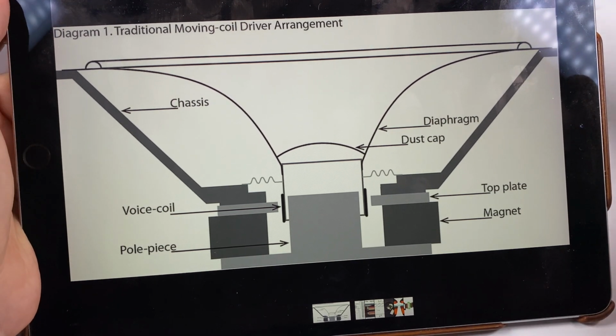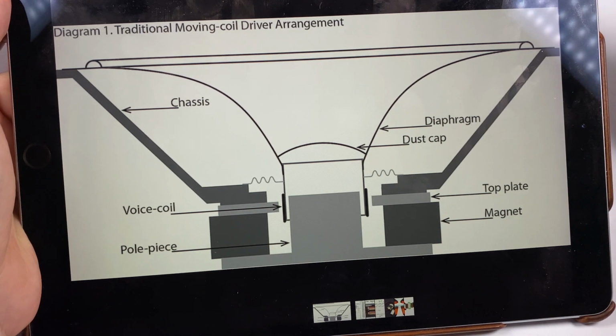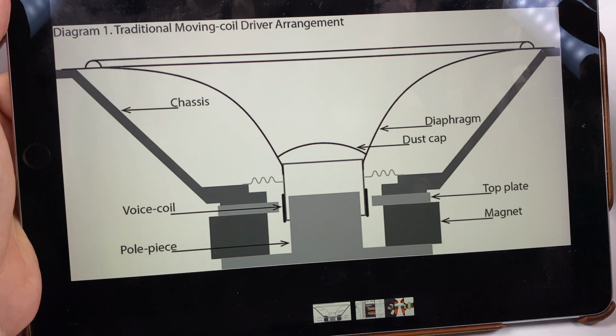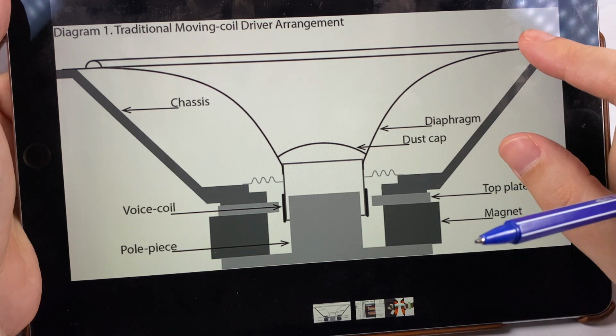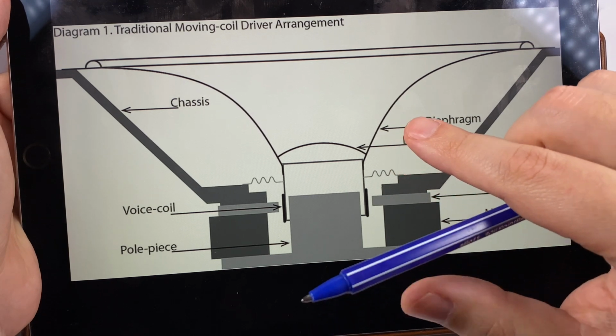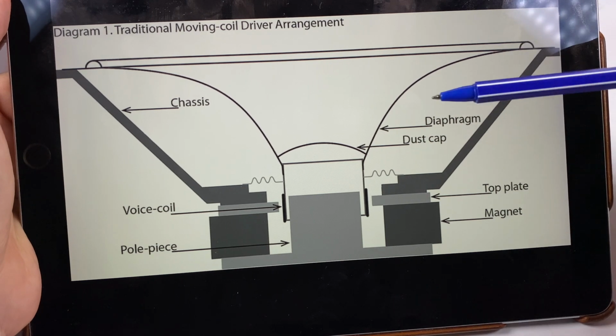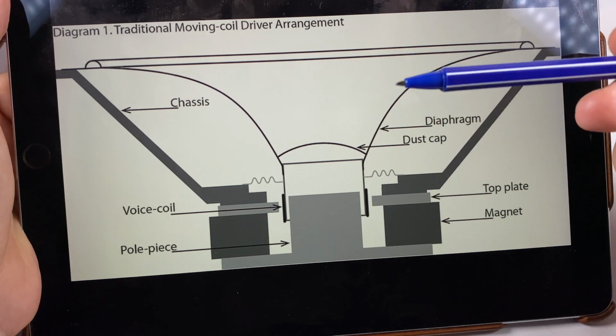So it's very simple, but why do we have so many different headphones? Why do they sound so different? There are a lot of aspects here, besides of course acoustic things like damping, open back, closed back design and so on. One of the factors that impacts the sound is that the diaphragm is not solid and uniform, and it can't move as one single piece, because we need to make it as lightweight as possible.